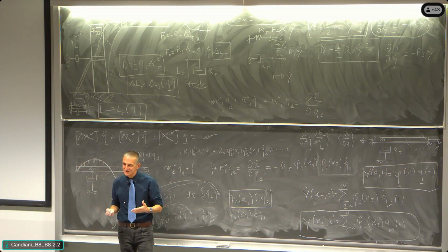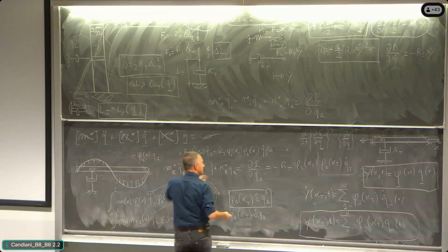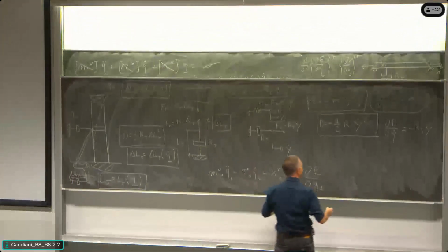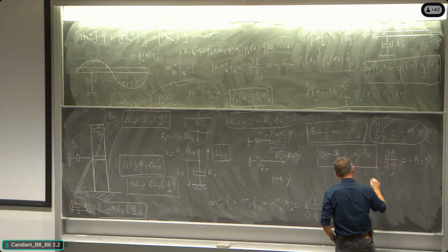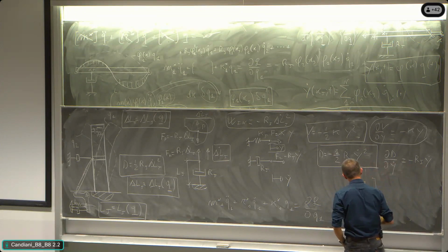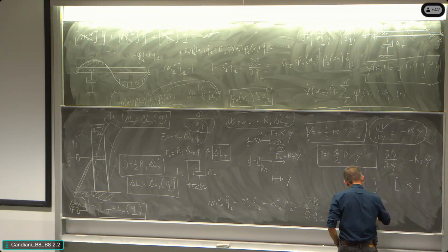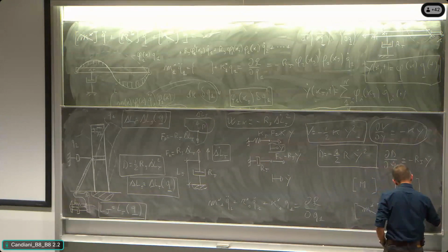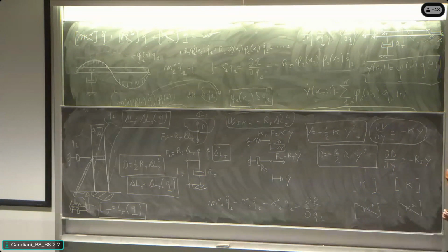And so from this evidence, Mr. Taylor said, all right, we make a very nice hypothesis, which is to say that I have a system that was modeled through n finite elements or whatever, n degrees of freedom. I have a mass matrix, M. I have a stiffness matrix. And then this mass matrix could also be the M star diagonal matrix of the continuum, or the K star diagonal matrix of the continuum, all right?